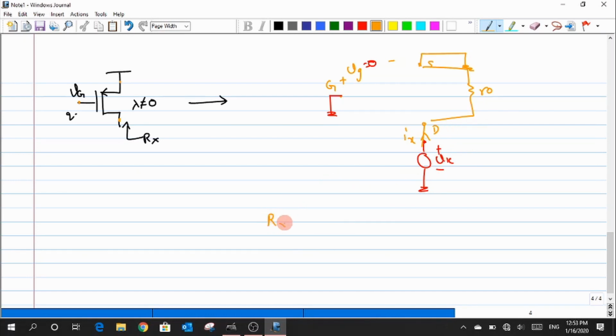So in short, the final conclusion is that whenever I have a drain terminal, the impedance that I am going to look into will be R0. But I will hold this particular statement for a while, and after then I will break this statement by adding some extra element to it. So as of now, when I am looking for an output impedance at the drain terminal, the output impedance that I would see is R0. This is with caution I am telling. It is not always.